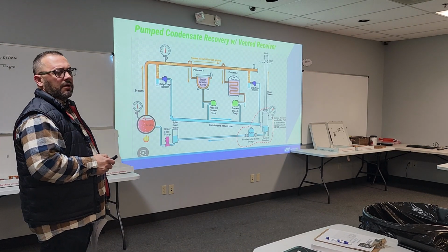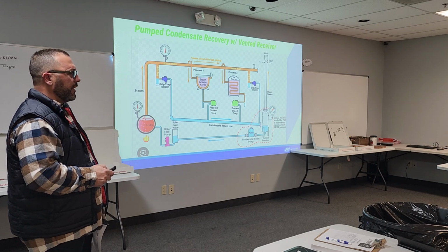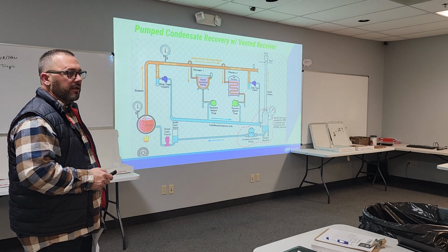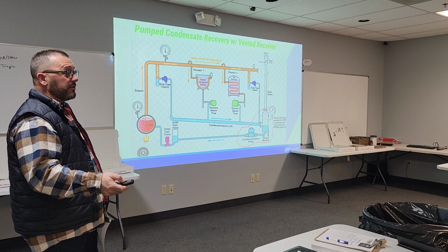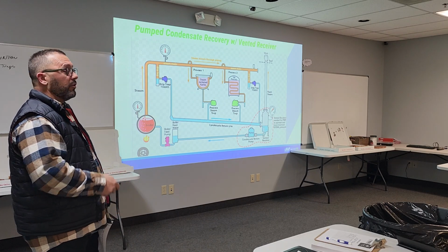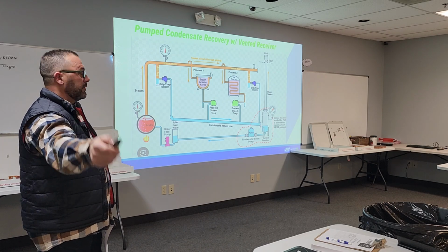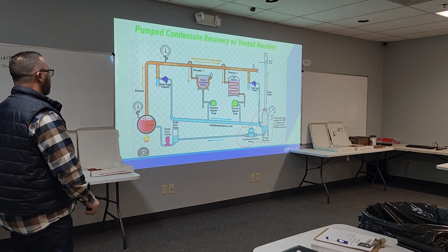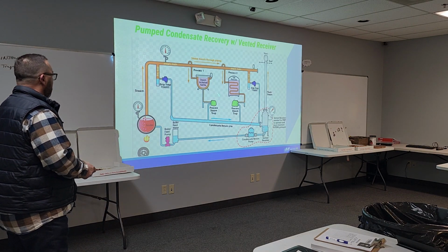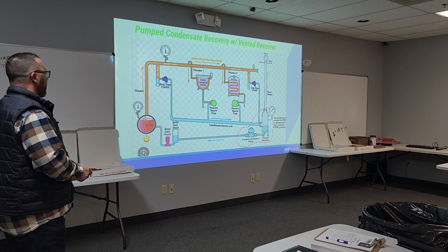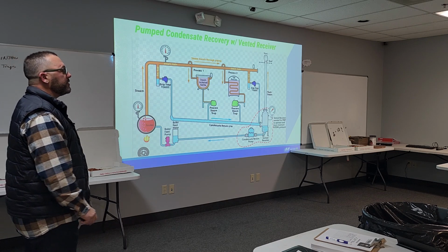They do a really poor job of venting air, and air is a big deal, especially on startup, or if it's not a steady, consistent process. So I'll just leave it at, I say process steam traps are just float and thermostatics.